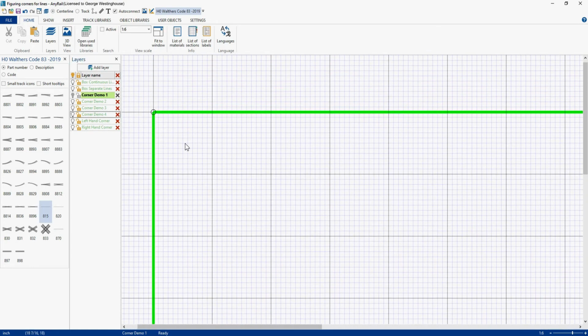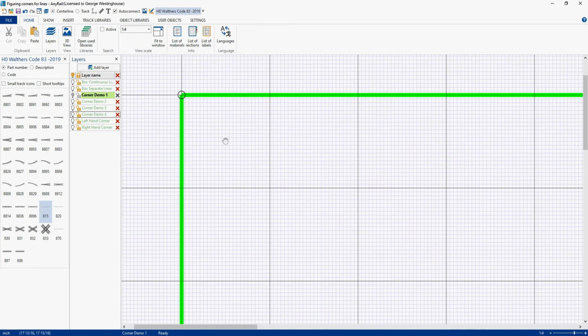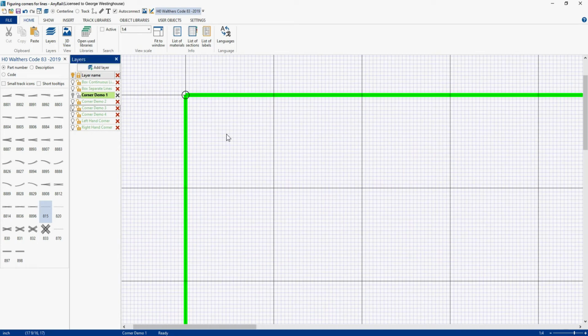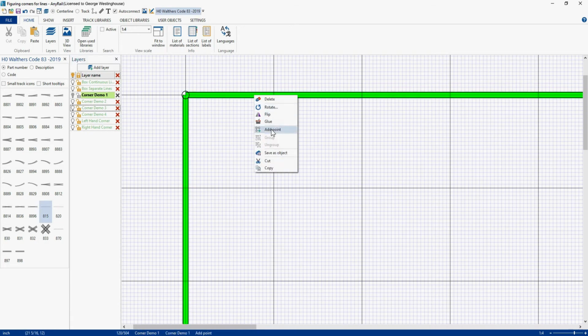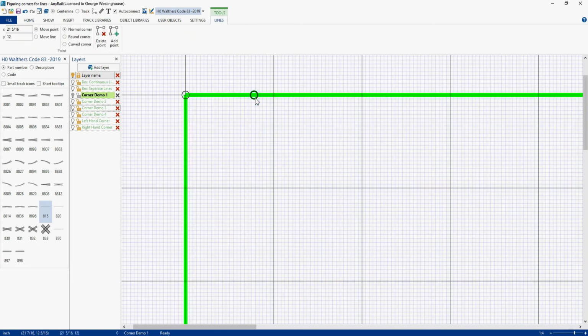So let's start putting in our coordinates. We want a 10-inch radius up here. Actually, we're going to put in a 15-inch radius up in this corner. So we have to move that in 8.875 inches from our starting point. And this is our starting point. I drew this way and all the way around and back to here. Let me just show you a couple real fast. We're going to put in a point, select that point, and set its X to 20.875.